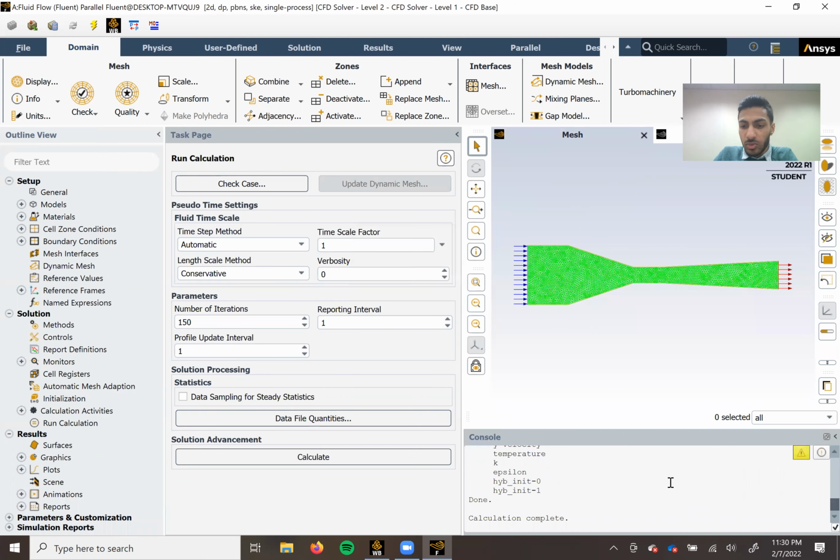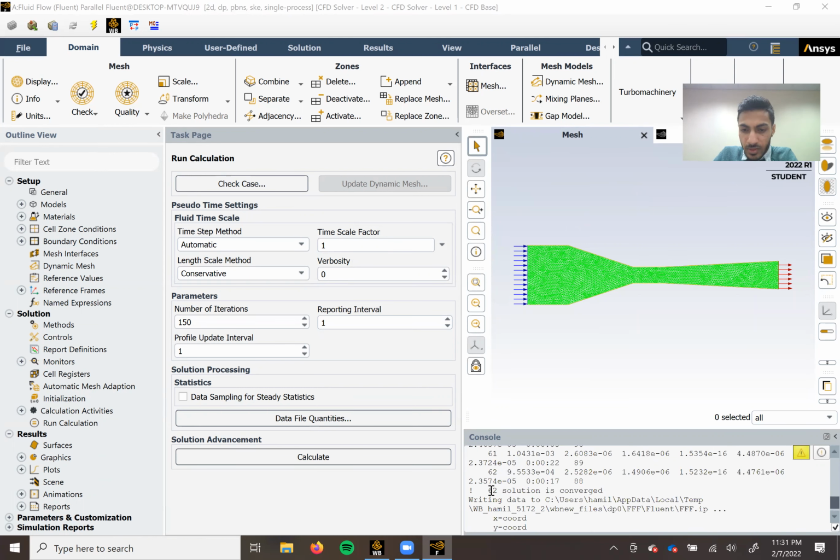So yeah, it didn't take all 150. You can actually go in there and take a look and see how many it took. It only took 68. If you have more meshes, it'll take longer. And then you might need to set the number of iterations higher if you're looking for a more precise result. For just the video, this is fine. When I did the project report, I still used 150 iterations, but I went a lot smaller with my meshes and actually ended up using all 150 iterations to get to that result.